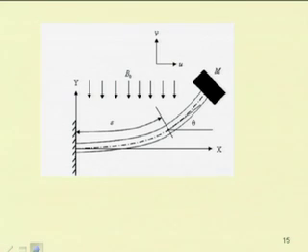So, for example, let us take different systems. Let us take a cantilever beam subjected to magnetic field. If it is subjected to magnetic field, then due to this magnetic field, if you have a conductive skin, a force and moment will be generated due to the eddy current set off in the skin. Already you know that in a magnetic field, if we have a moving conductor, then a current will be set off in the conductor, and also we know in a magnetic field, if we have a current carrying conductor, the conductor will be subjected to some force. So, due to these effects, the beam is subjected to a force, axial force and moment.